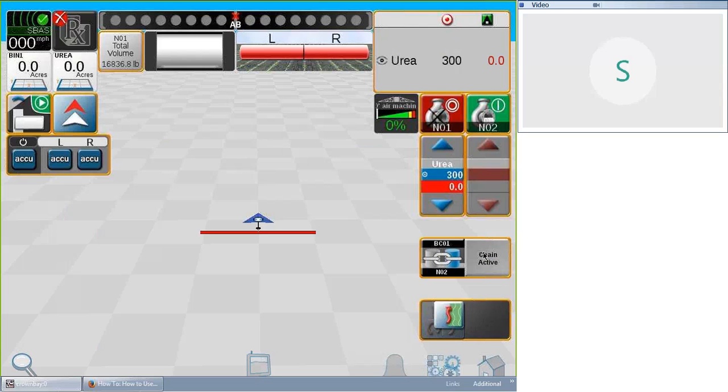The other things our chain widget can do is it's a multifunction. So a chain does not go in a circle. Once we empty, in this case, bin 2, and then we empty bin 1, we're going to have to manually reset that chain to the original order if we have more application to do, if we got to go back and reload. So we got to set it back to the original order so we can go bin 2 and bin 1 again. If we forget to do that, it's just going to run out bin 1, because that would have been the last bin in the chain, and it's going to shut down. It's not going to switch back.